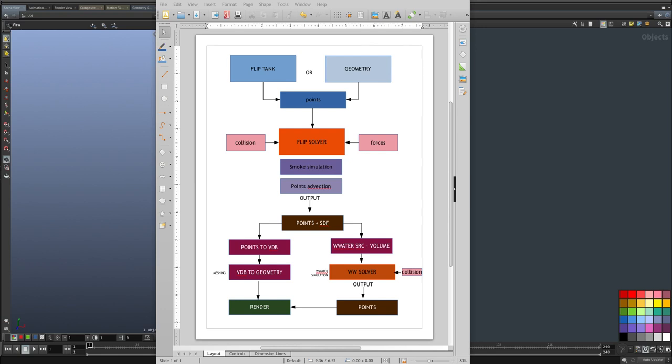So basically what happens is we feed our points, the flip fluid runs the smoke sim internally to solve the pressure, decides how much velocity there is, pushes the voxels in the right direction, and then takes a set of points and advects them through that volume. And the idea with flip fluids is that we need nicely distributed points at any point in time, and this is where the flip fluid does its magic. Basically it gives us a nicely distributed set of points that we can convert into a mesh later.